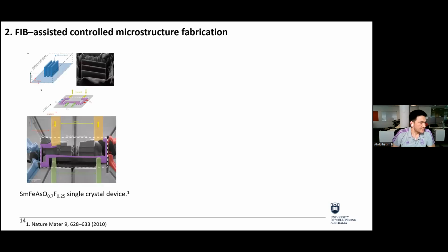And the second part is, we know topological insulators have surface states, and according to some calculations, surface states usually appear in the top 3 to 5 nanometer depth. So what I have found is that maintaining the crystallinity of surface states is really important when fabricating a device using focused ion beam, because, as we discussed before, antimony telluride is really sensitive to the ion beam, so even a very small amount of ion beam radiation can cause damage and amorphize the surface.